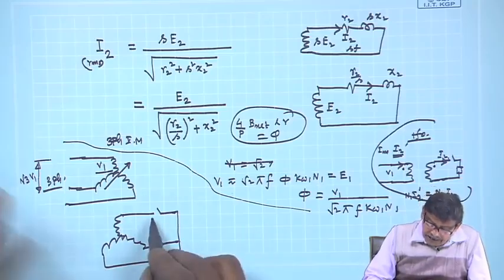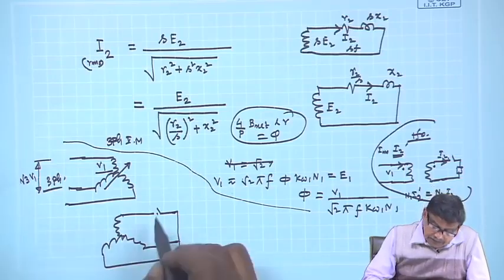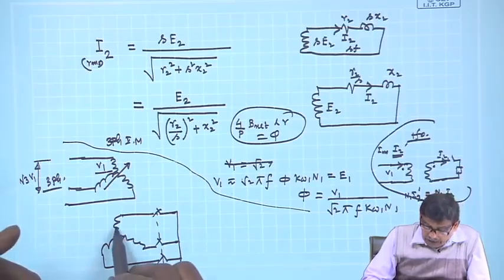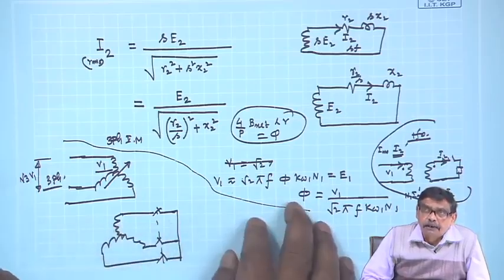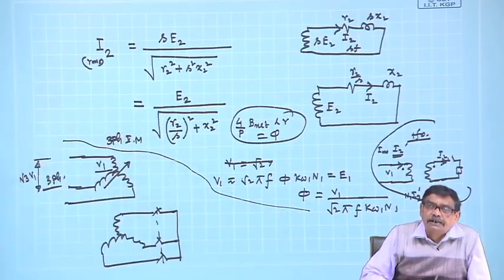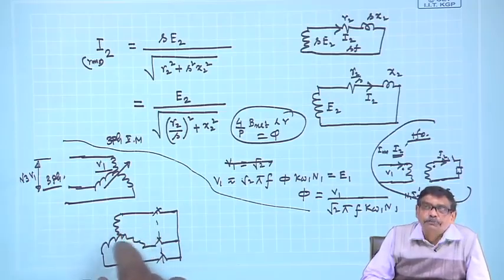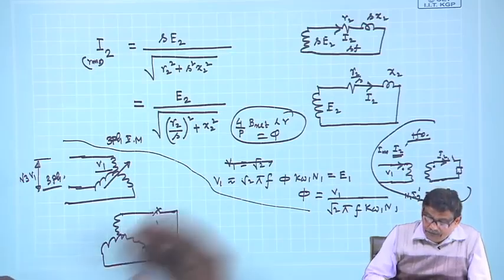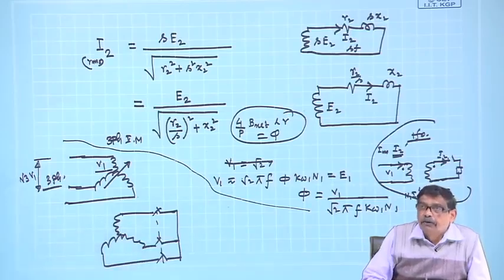Now, on one hand flux per pole has to remain the same, and on the other I will close the switch, and therefore there will be secondary current. Now, there is a second player coming into the picture apart from the stator to dictate terms, that is its MMF should also be taken into account, is it not? Flux per pole, how then can it remain constant?